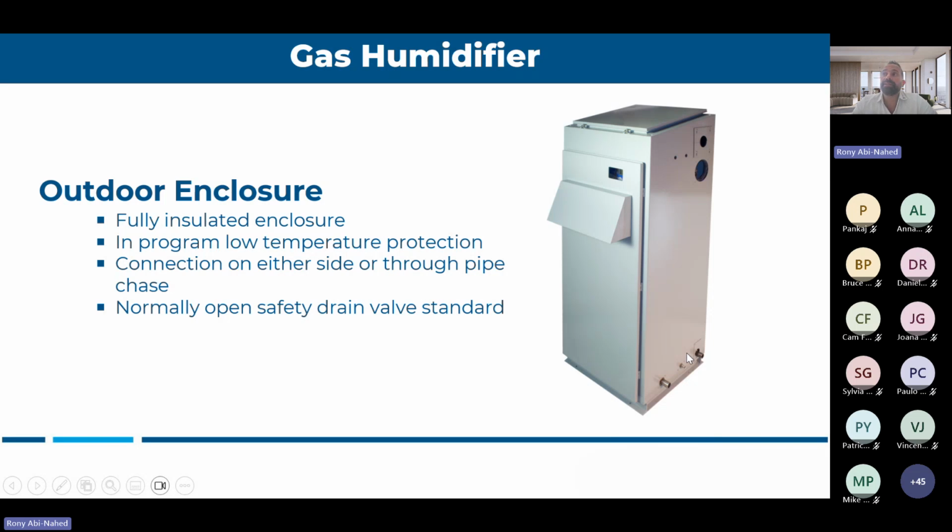Now, the big question is, is it safe to have a gas unit outside in cold weather? Yes, because depending on the manufacturer, everyone has their own protection to make sure that if you lose power at some point during winter, you don't freeze your unit. Most of them will use a normally open valve, so if you lose the electricity, you drain your whole system.